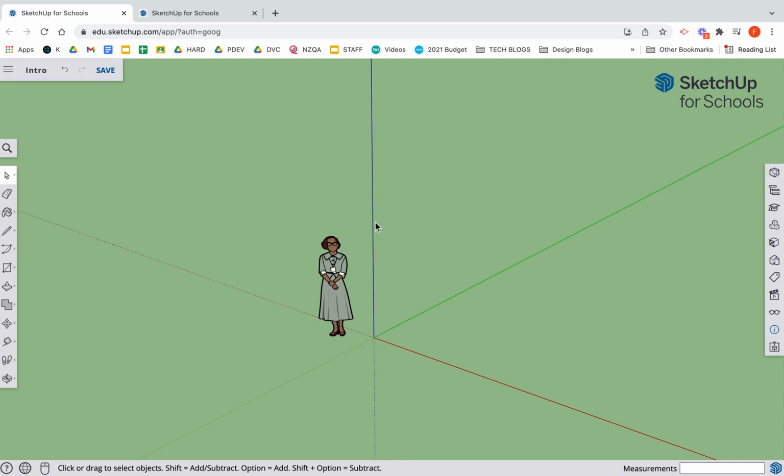So we are going to be drawing some basic forms today, using our selection tool, which is the spacebar, and the R on our keyboard to get the rectangle tool, which you will see here. We also have lots of other shapes, and another quick shortcut is C for circle.